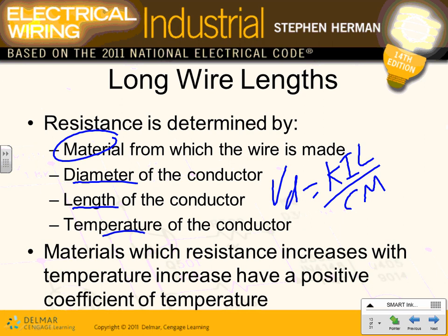On feeders, typically, if you have a big facility, like a 150,000 square foot building, and you need to take feeders everywhere in that building. Our building is 25,000 square foot. That's a small building, very small building, size-wise. So for voltage drop on feeders, if you use 1.25 to size the conductors and use THHN conductors, you're almost done; typically you don't have an issue with that.